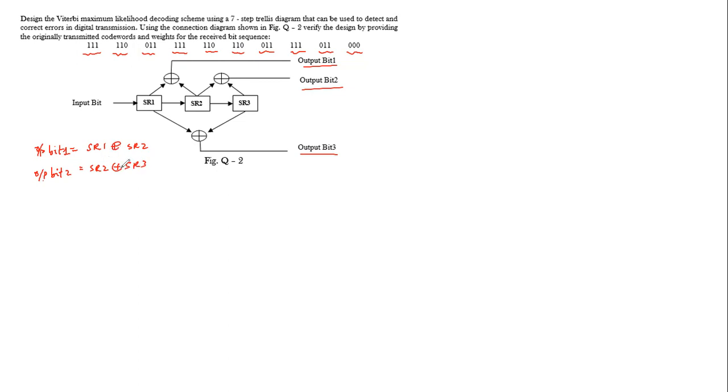Yeah, this is modulo 2 addition, right? More like an exclusive OR, right? Then output bit 3 is the same as the shift register 1 plus the shift register 3.